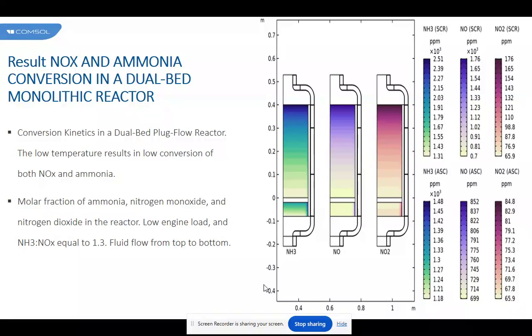The first automotive converters typically had 400 CPSI, but in the past two decades or so, there has been interest in monoliths with higher cell densities of 600 or 900 CPSI. The nominal wall thickness is traditionally reported in thousandths of an inch, with a standard value being 6.5. Improved technology has allowed thin, about 4.3 mil, and ultra thin, about 2.5 mil walls. Monoliths with a higher cell density typically have thinner walls. The washcoat typically occupies about 12% by volume of the monolith.